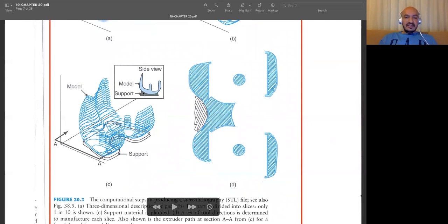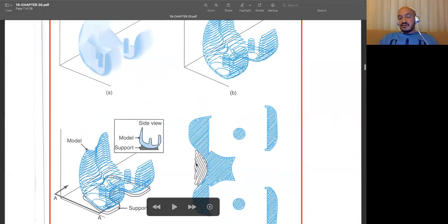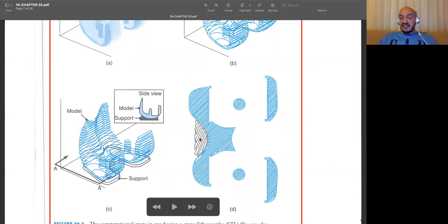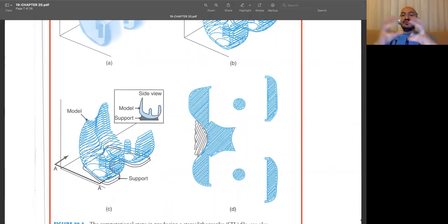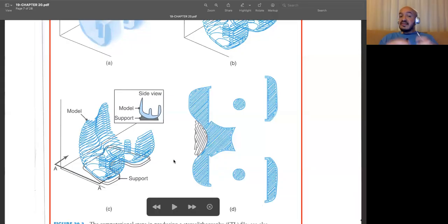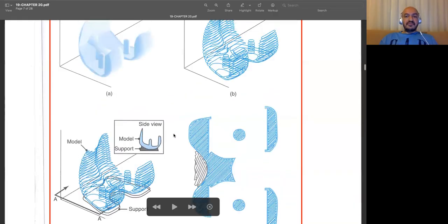This is represented here by using gray or black color. You may use the same material for the support structure generation, or use different materials. You may even use some water-soluble support structures, so that once you manufacture complicated parts, you can simply put your part into a kind of water pool, and if you wait for some time, later these support structures will be dissolved, and you will be left with just the desired part. You will be just left with the blue part.